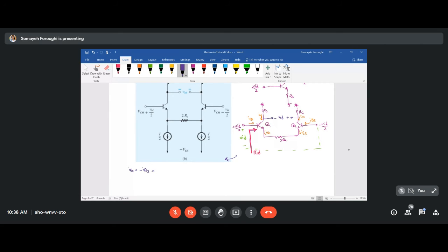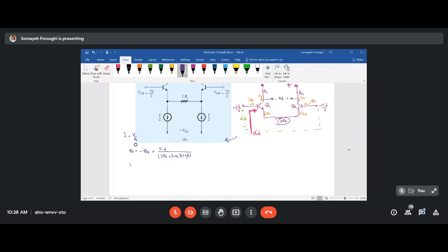And it's like having the total voltage over the total resistance, I is like V over R. The total resistance from the base of Q1, so you have 2 RE and 2 little RE, all times 1 plus beta, coming to the base of Q1: 2 RE plus 2 times little RE times 1 plus beta. And about IE1, it should be negative of IE2.